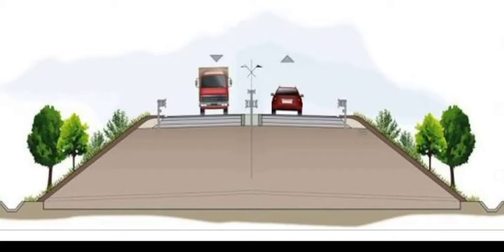So the main components, if we see, are embankment, subgrade, drainage layer, shoulder and pavement layers. Apart from these five layers, we need to provide the side drains and other specific drains, such as a capillary cutoff, right, so that it should not affect the upper layers.